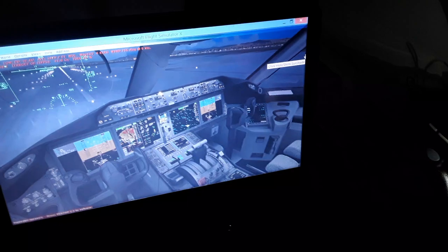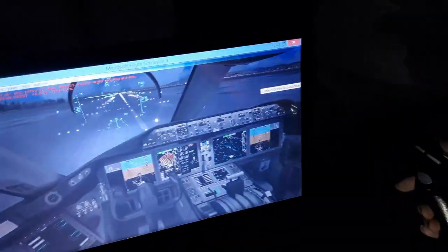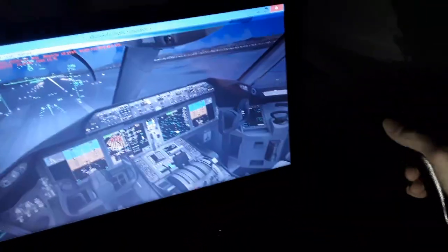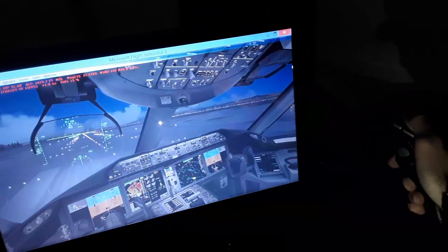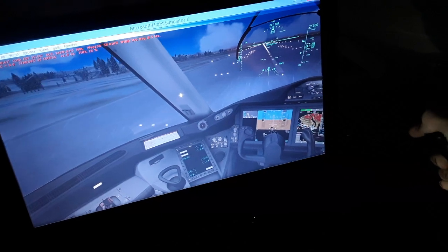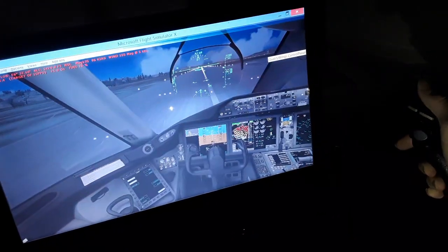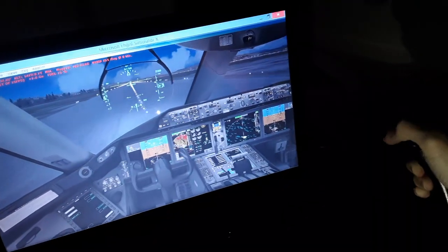You can see here we have the thrust levers. We advance, takeoff, ground, and parking brakes off. We can use also here the thrust levers, the side stick that I have. So we use full takeoff, and we press the side stick down or the yoke until 80 knots, also align with the rudder pedals, some rudder input, because we have some side winds.